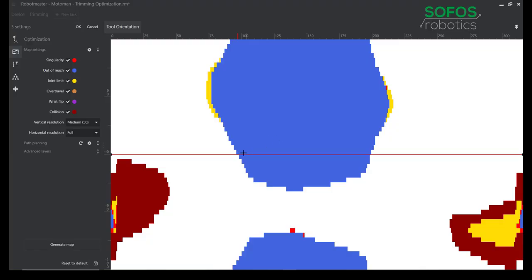And we're seeing here exactly what we saw in that simulation, which is about halfway through that tool path, our tool disconnects, and it's this blue blob, and that is indicating that it's out of reach. Now what's really great about this is we can manipulate this line around these blobs, and then it will put the correct rotation around the z-axis of our TCP frame.